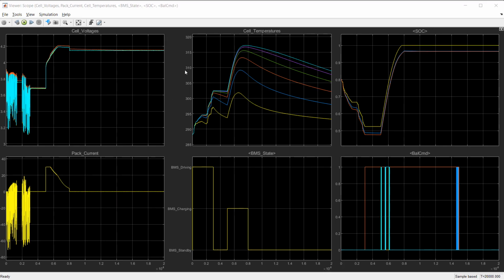Since we calculate the current limit based on the maximum resistance value within the battery cell lookup table, we're being conservative. A less conservative current limiting calculation could use the actual battery cell resistance at the estimated SOC and temperature, since this information is available at all operating conditions.